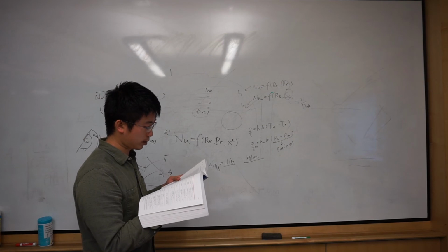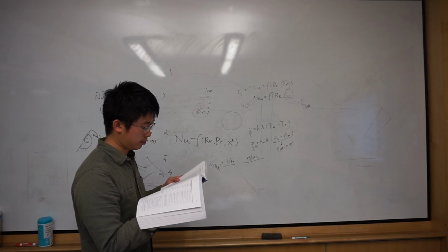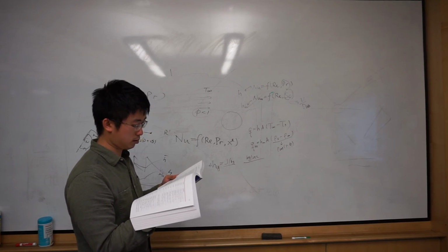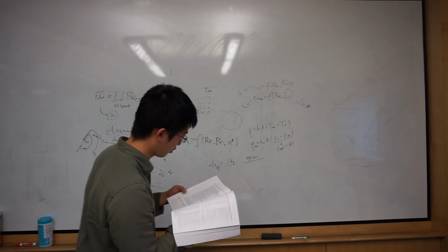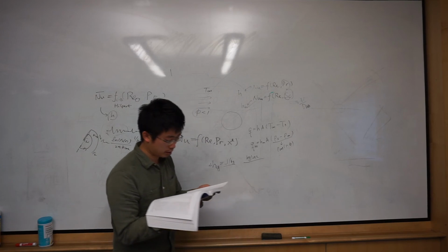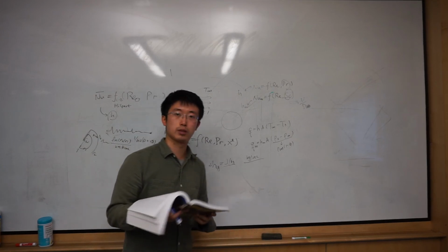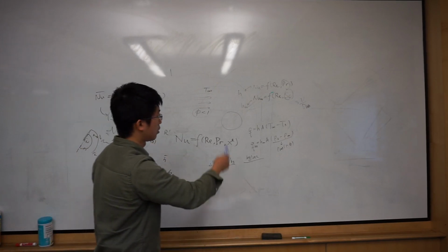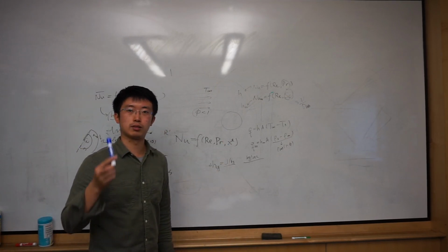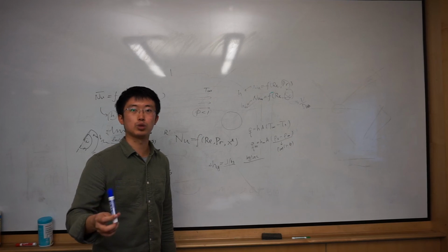What manifests boundary layer separation from a circular cylinder in cross flow? How is separation influenced by whether the upstream flow is laminar or turbulent? This one we also talked about. After the separation, the heat transfer is greatly reduced.